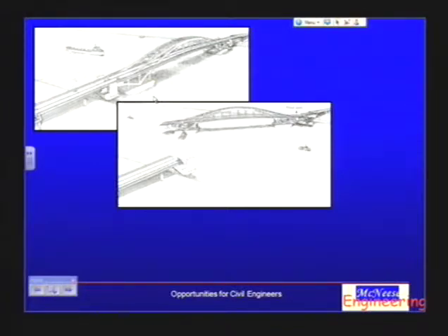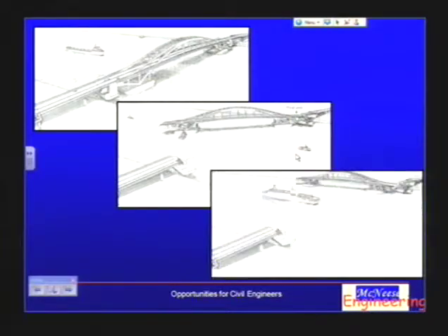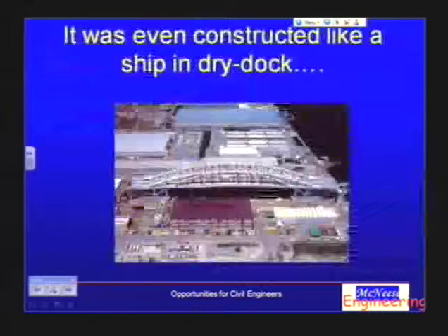And so when we need to get it open, we'll just have a tugboat just kind of push this thing open. It pivots over on this other side. Boats can travel up and down through it. And then when we want the traffic to go across, we just push it back shut. Okay? Too big of a span for a traditional drawbridge type bridge, and so we actually create a floating bridge that we can move out of the way.